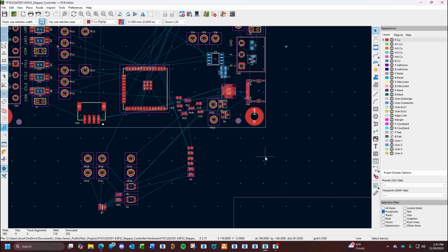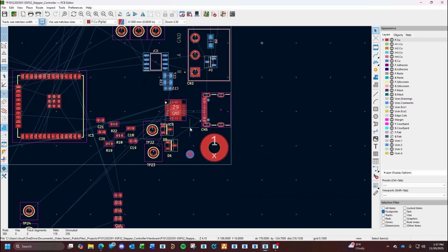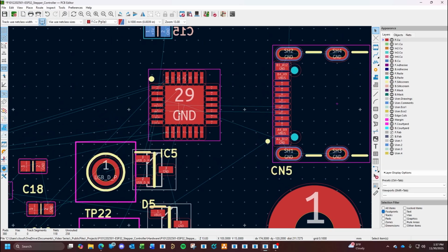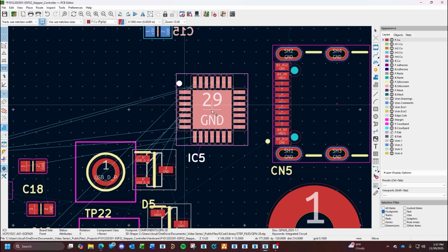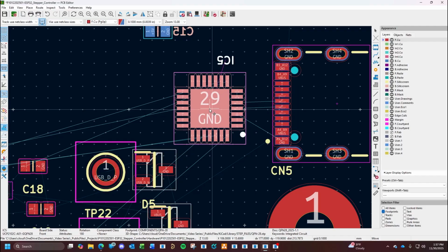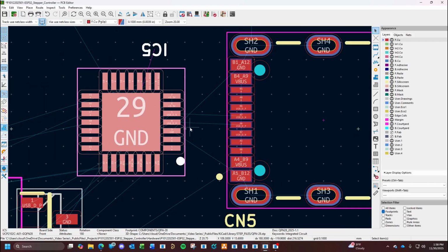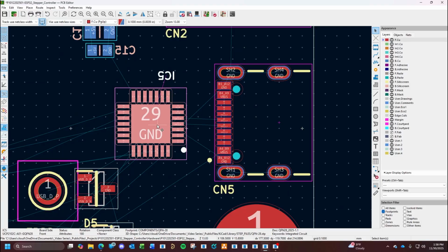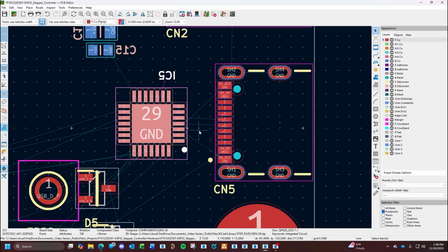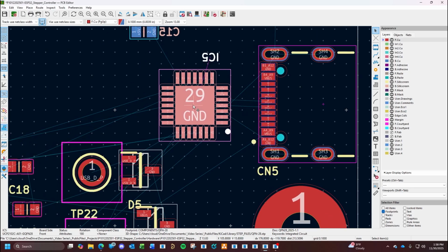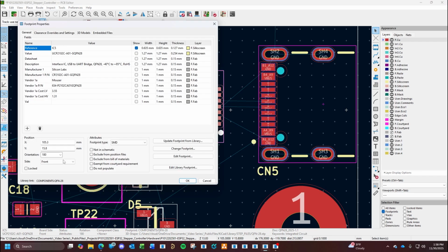So now we have quite a few components. We'll probably populate on the bottom side for a lot of this. So let's see what we got. Getting USB, so see how this looks here. We'll leave the actual bridge chip up here. The USB positive, negative, we're going to try to line up to get some better straight traces. We're going to pull that back.